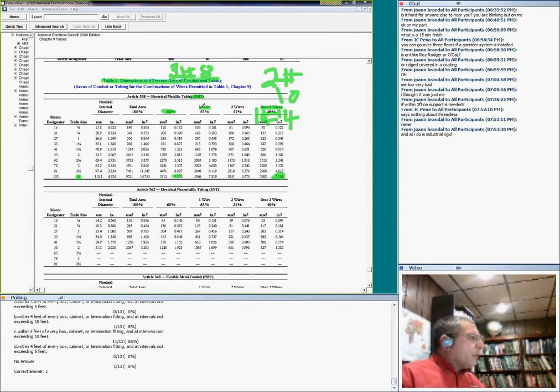If I have one cable, one type of conductor cable, I can go all the way up to 7.81, a little more. If I have 2 conductors or 2 cables, I can go all the way to 4.573. Any questions, guys, about reading this table? That's how much I can fill legally if I'm to use an EMT conduit. Underneath it, there's the EMT, and if you look underneath it, that's MC, and it keeps going all the way through all the recognized conduits in the code.